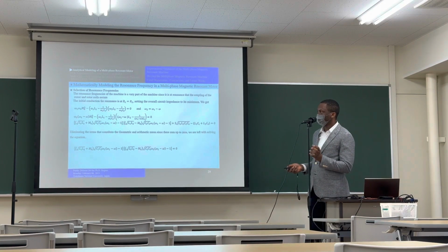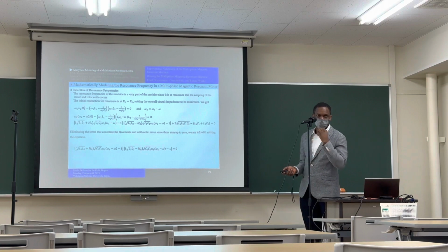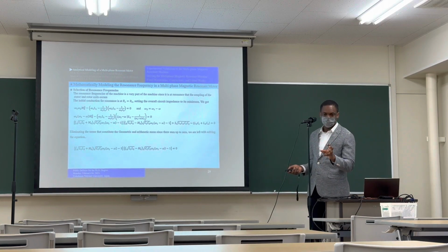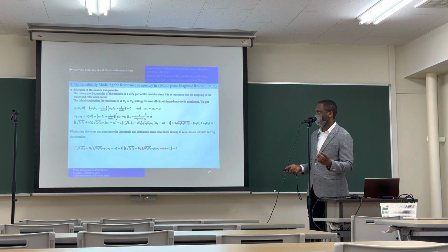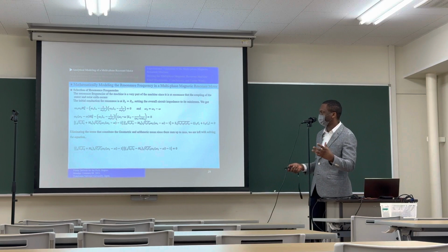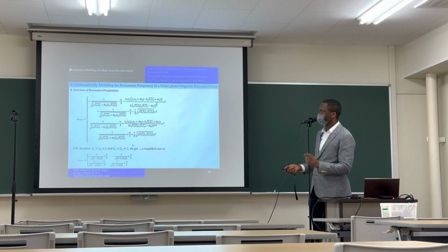We want to see how we can calculate the resonance frequency. But the most important aspect of this is how to estimate the capacitors that we have to add to the coils during resonance, because we choose the resonance frequency as the target frequency. If we do more analysis of the circuit, then we have the resonance frequency in this model.